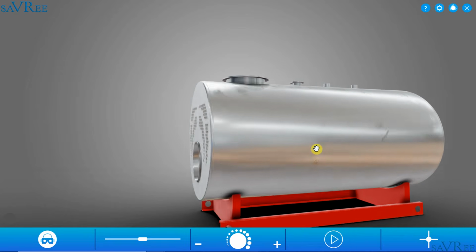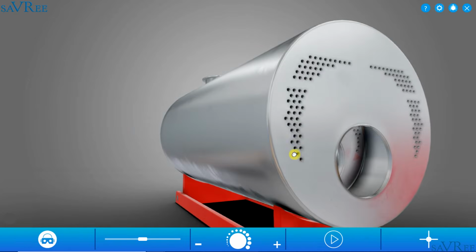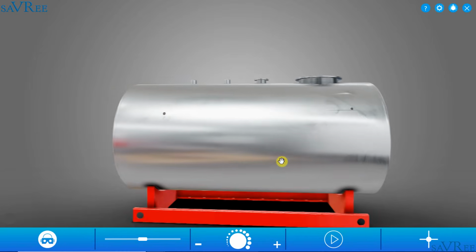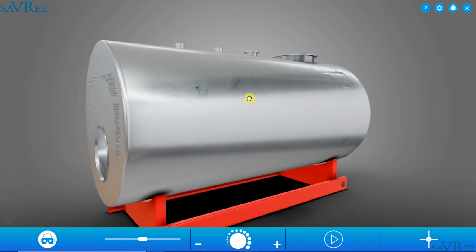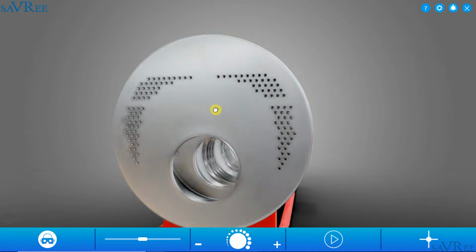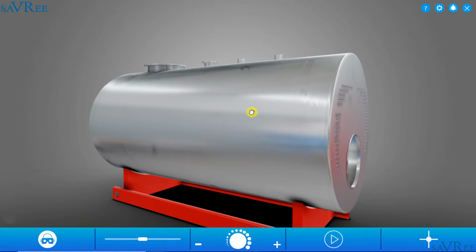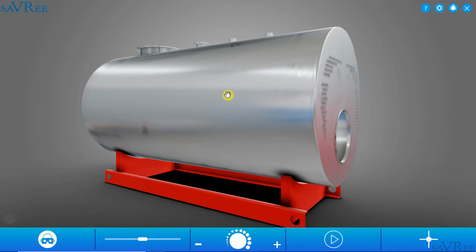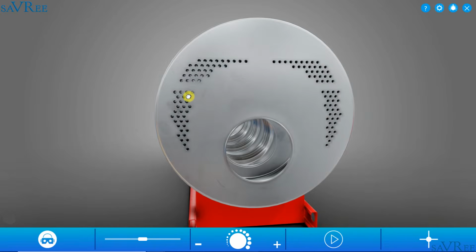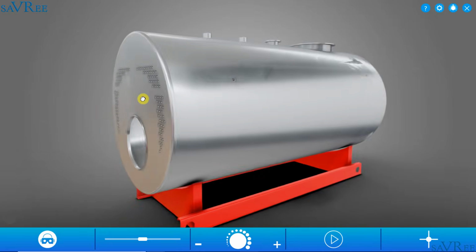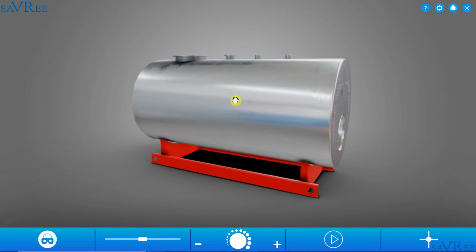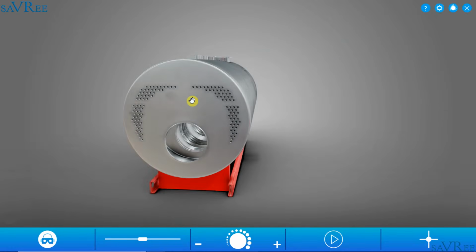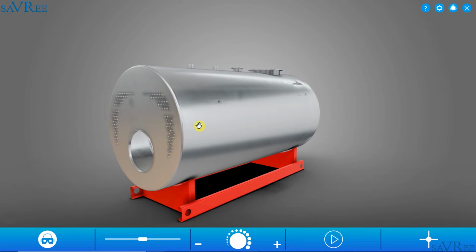And you can see we've actually got quite a simple design now. It's just a long cylinder, more or less. So we've got a cylinder. We fill up the cylinder with water. We've sealed the exhaust gas system, so it's not going to mix with the water. And once we fire up the boiler, we allow the exhaust gas to pass through the furnace and the tubes, etc. Then we'll transfer the heat to the water, and we will turn it to steam. But as you can see, the boiler design is relatively simple when we break it down into its major components.